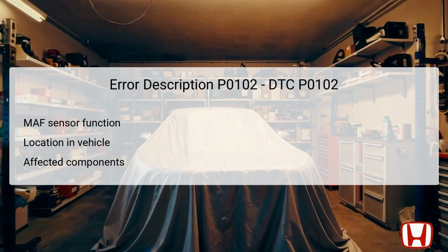In addition to the MAF sensor, the intake air temperature IAT sensor may also play a role in this circuit, as they often share connections. Worn wiring, poor connections, or a malfunctioning sensor can cause low voltage outputs. Therefore, understanding these components and their locations is essential for effective troubleshooting.